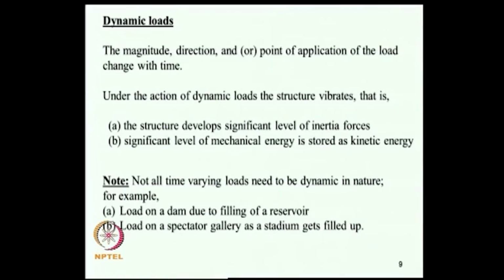Now, I want to emphasize that not all time varying loads need to be dynamic in nature. For example, load on a dam due to filling of a reservoir, it takes place so slowly that the accelerations that are developed in the structure are so low that the corresponding inertial forces will be significantly less than the static loads. So, it is not a vibration problem in this context.